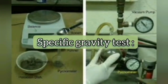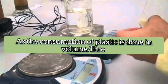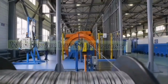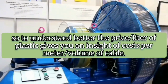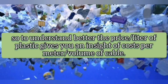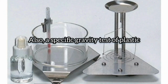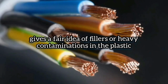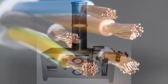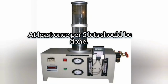The specific gravity test of plastics. This test is very important to cable cost optimization, as the consumption of plastic is done in volume, liters, whereas you buy it in kilograms. So to understand the price better, liter of plastic gives you an insight of costs per meter volume of cable. Also, a specific gravity test of plastic, generally called density, gives a fair idea of fillers or heavy contaminations in the plastic. Limiting oxygen index should be done at least once per 5 lots.